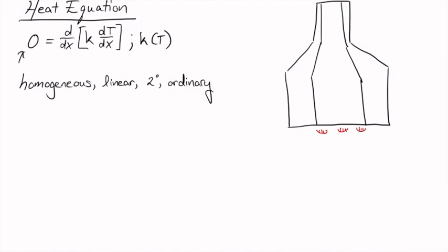To solve those boundary conditions, we need to look at the specific geometry of the problem. Here's a schematic of a furnace. If you have to design one for your D2 project, you will find my schematic rather impressive. Heat's flowing from inside the furnace outside, so we'll set our coordinate axis in that direction too. It's not required, but we'll say that x equals 0 is that inner wall, and x equals 1 is where the end of the cement wall is located.